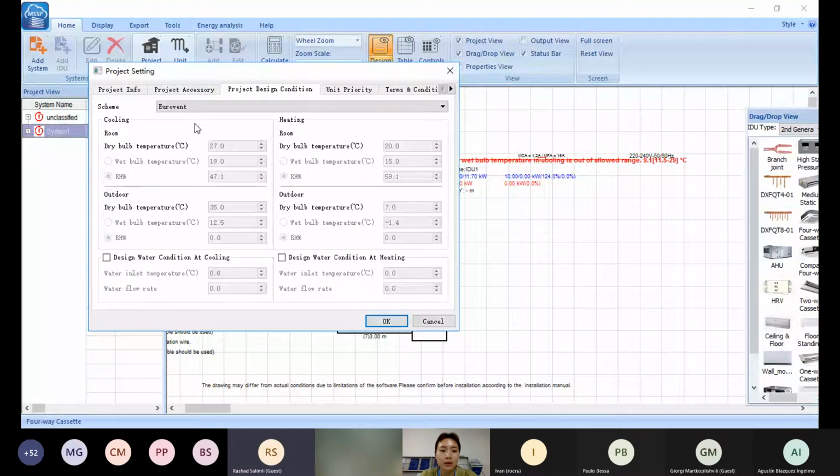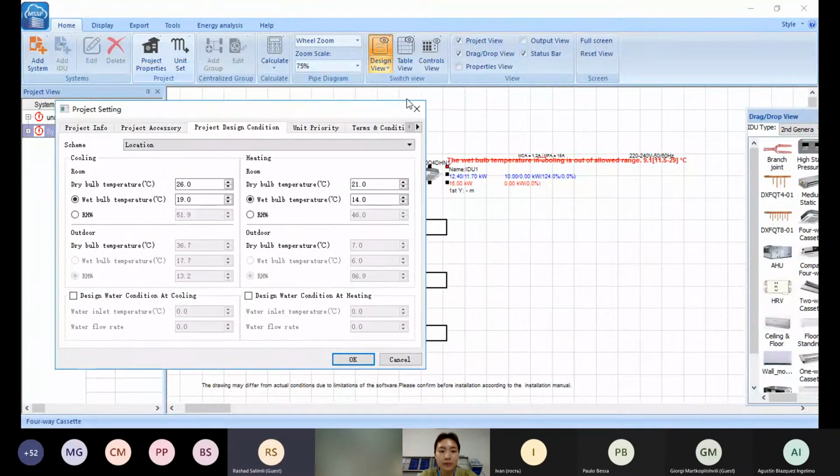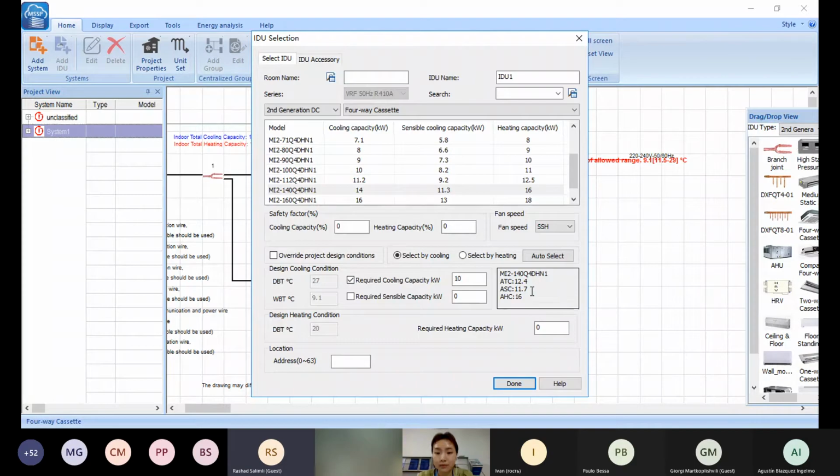I'm sorry, I'm interrupting. I just want to ask a question about this capacity selection. You may know that in HAP, the hourly analysis program which most designers use, the sensible capacity and the total capacity are so close to each other. When we select the indoor unit with the sensible capacity, the total capacity is bigger, and when we use the total capacity, the sensible capacity becomes lower.